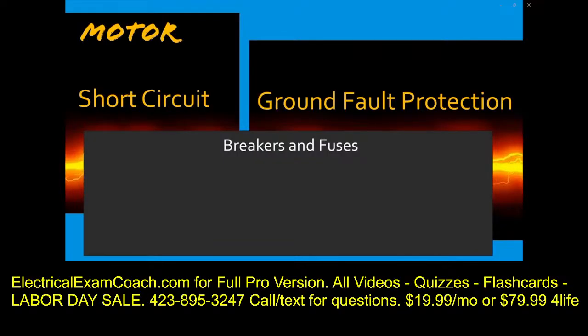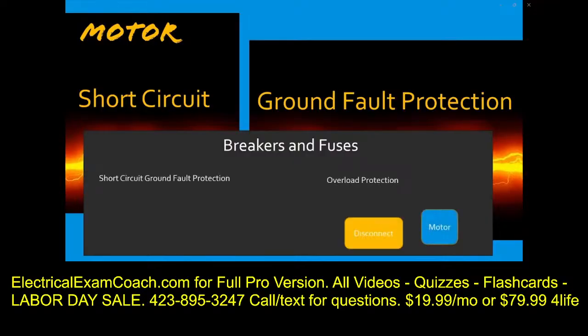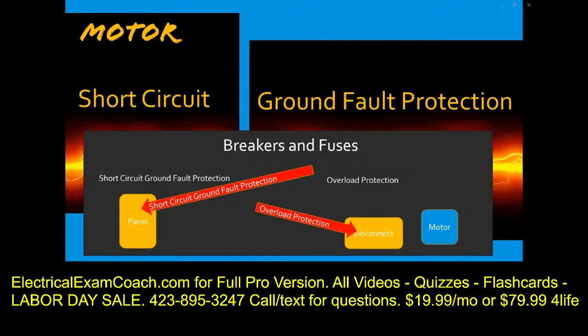Okay, so we have both the types of protection. Let's imagine that this is a motor. Next to the motor, there's a disconnect. And then feeding that disconnect, there's a panel. Okay, at the original panel is where you're going to put your short circuit ground fault protection. At the disconnect is where you're going to put your motor overload protection.